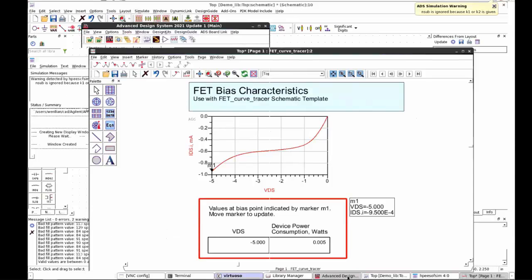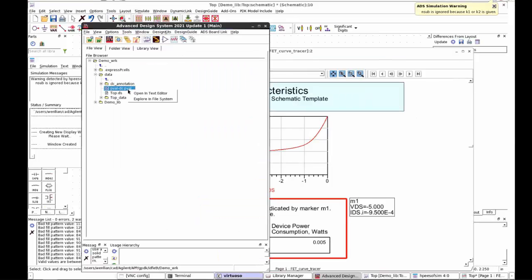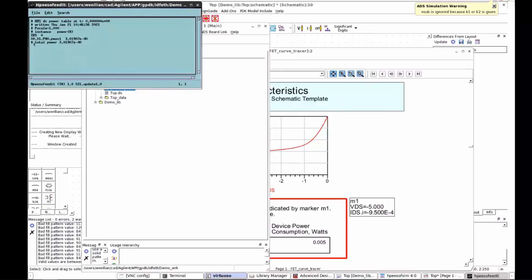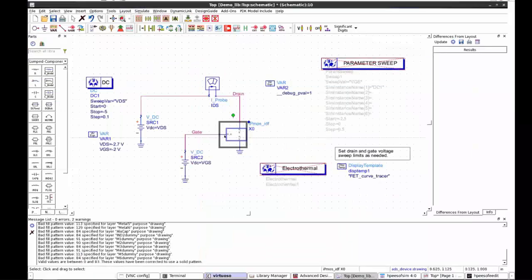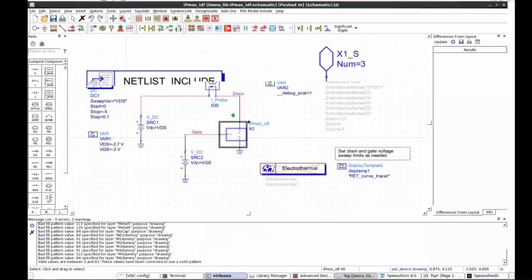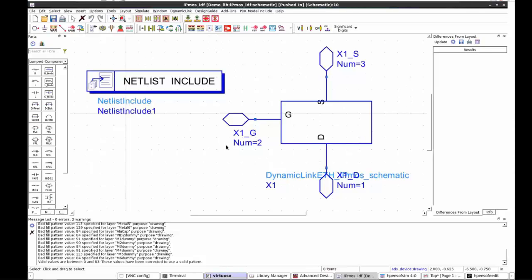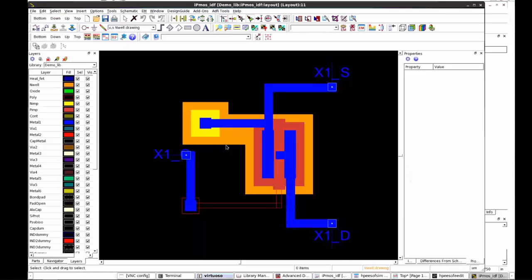Okay, now we can go up here. So you see this is the top level, right? S0.S1.PMOS, right? Now I explain to you how we do the name. Now let me go back to the top level and push it down. To find this guy's equivalent layout, you can use the hot key, Shift Control L, right?